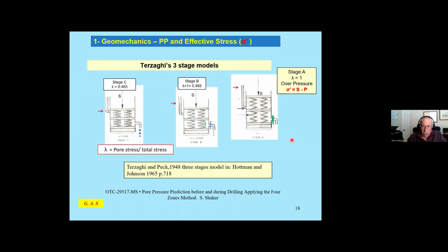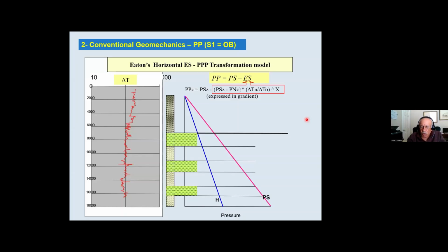So in this case, on this stage, the fluid and the spring carry that stress. And he came up with the idea they call the effective stress, the same as effective porosity and effective permeability. Effective stress is the main stress on the cylinder on the top minus the pore pressure. And that's how the idea of pore pressure came to birth.